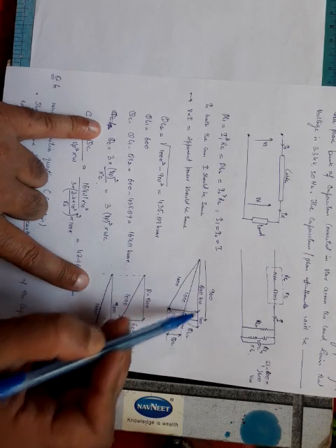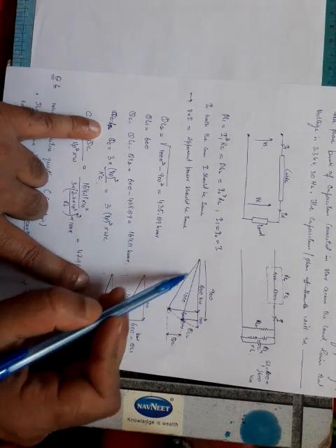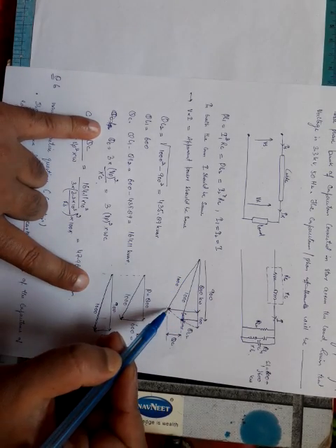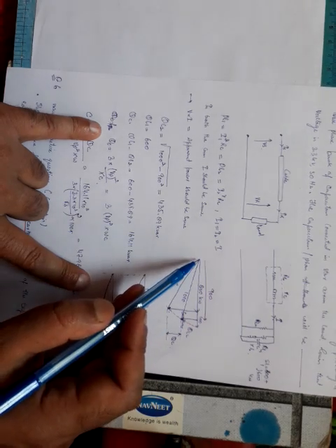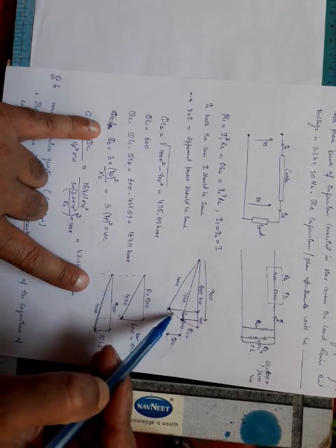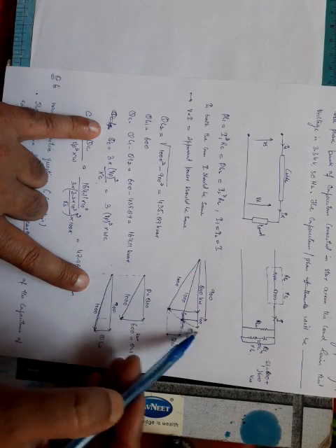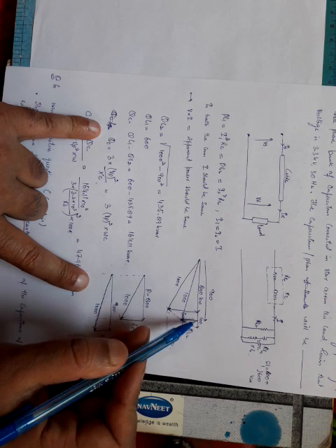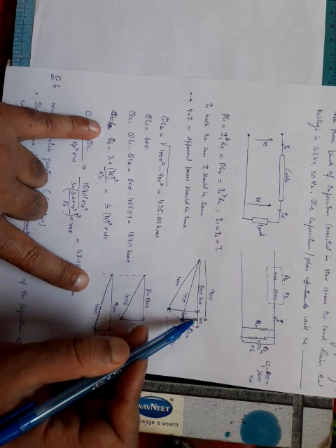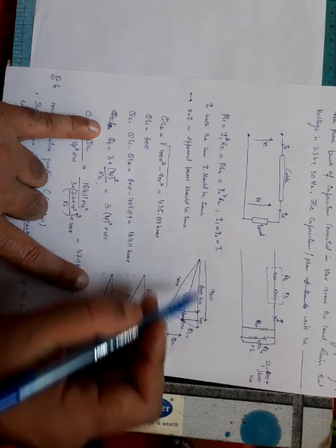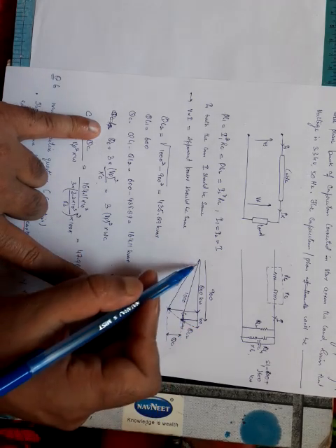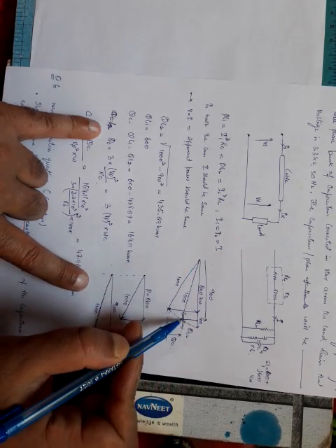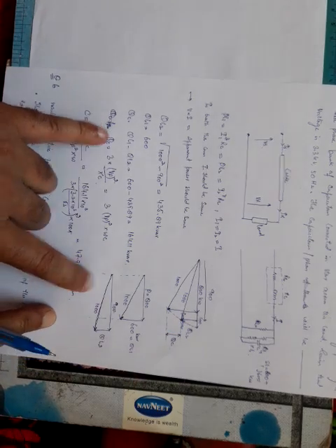This is 800, this is 600, and this comes out to be 1000. Now I will draw an arc with this as center, whose radius is equal to 1000, and draw it like this. So from here to here, sorry, it is plus 100. That means 900. From here to here it is 900. So I can draw this apparent power like this. It will be again 1000.